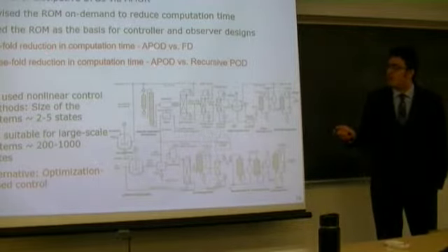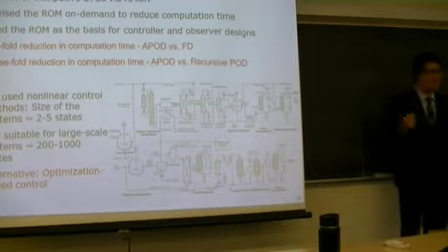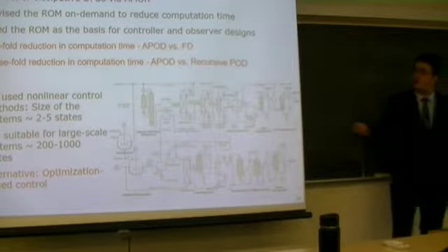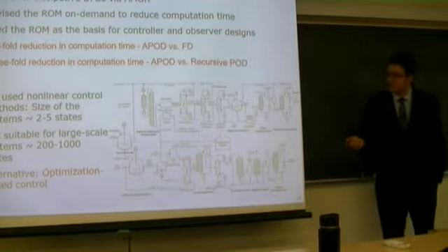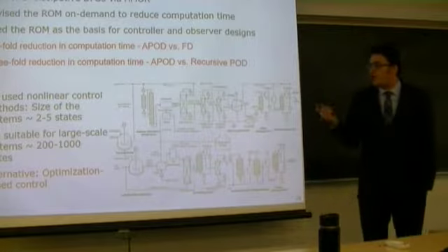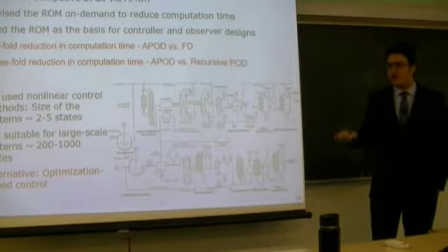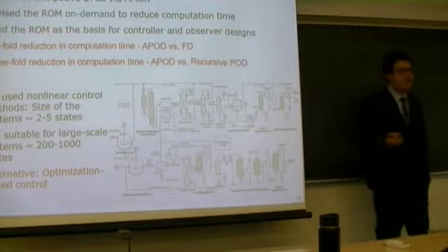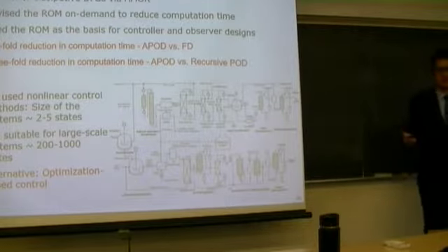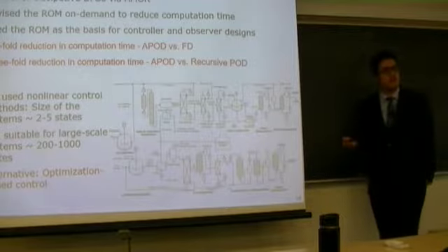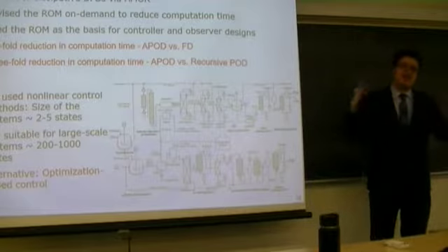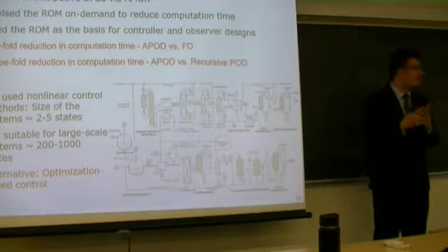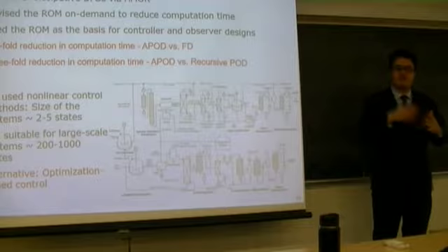And when we compare our methodology with just the traditional recursive proper orthogonal decomposition, it results in a 3-fold reduction in computation time. The important issue here is, as you may recognize, the controller was designed based on nonlinear control methodologies. So such a Lyapunov-based controller is very limited by the dimension of the system. Theoretically, we could use it for any type of system with different dimensions.